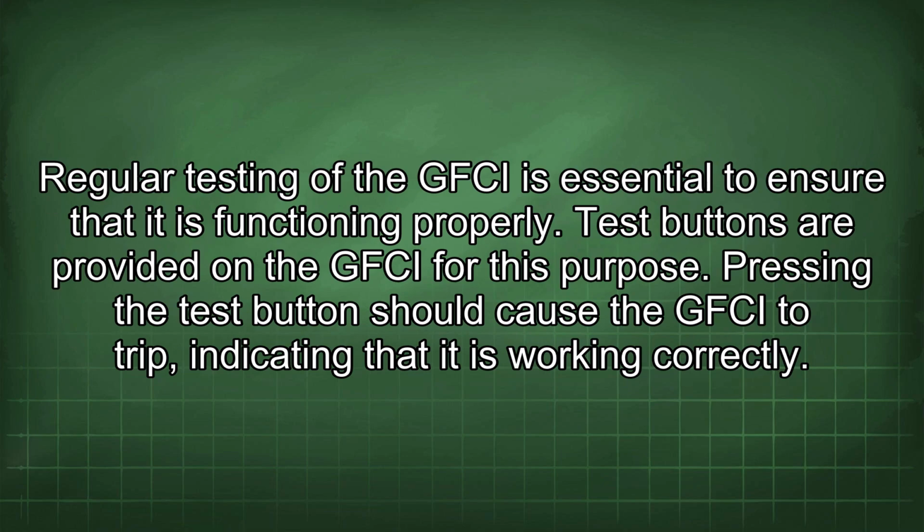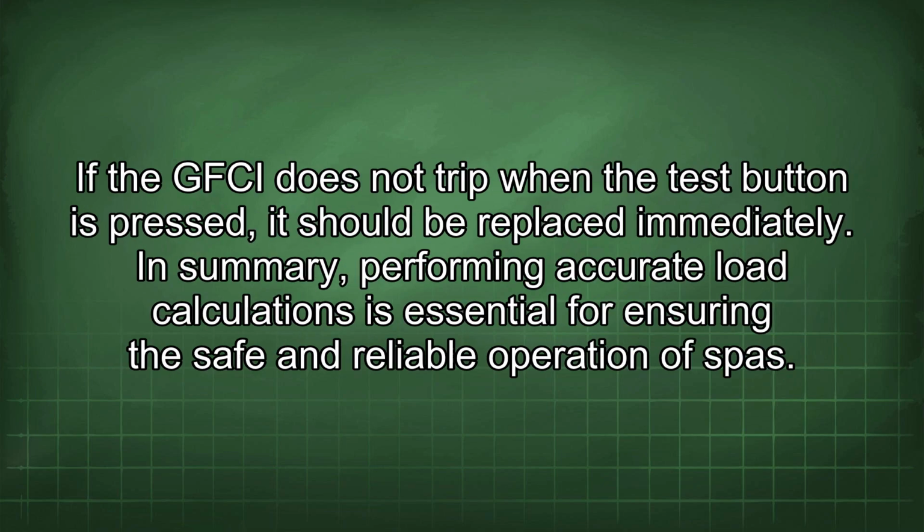Regular testing of the GFCI is essential to ensure that it is functioning properly. Test buttons are provided on the GFCI for this purpose. Pressing the test button should cause the GFCI to trip, indicating that it is working correctly. If the GFCI does not trip when the test button is pressed, it should be replaced immediately.